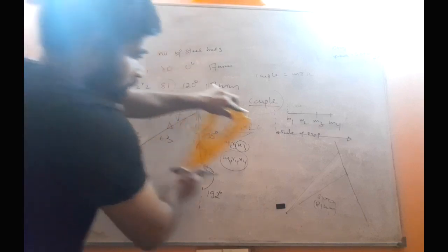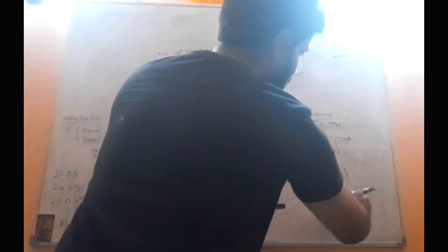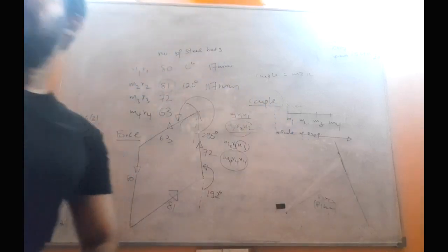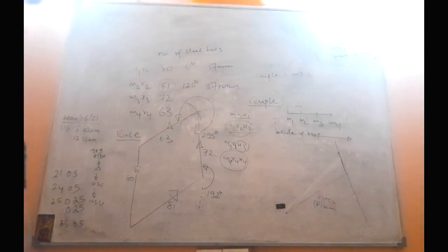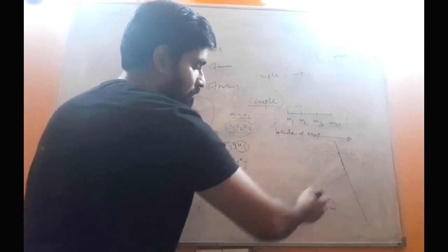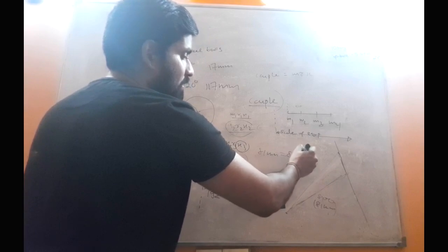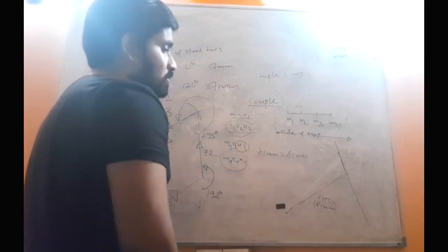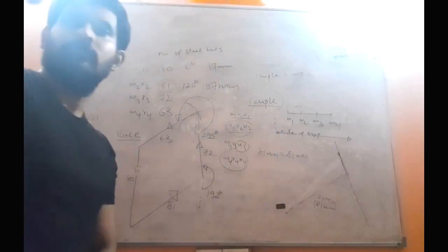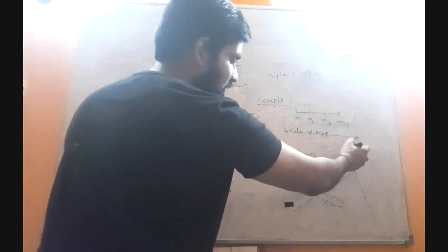It is parallel to this one, and this one parallel to this one, because now we know the scale. If you consider this vector, this 81 millimeter line represents 8100. So just measure this length in millimeters.